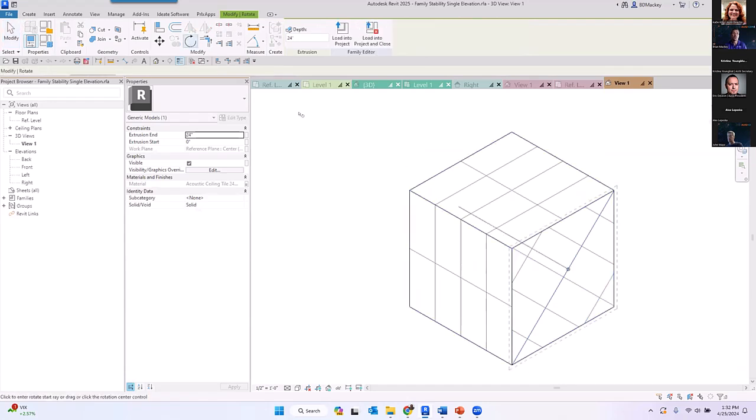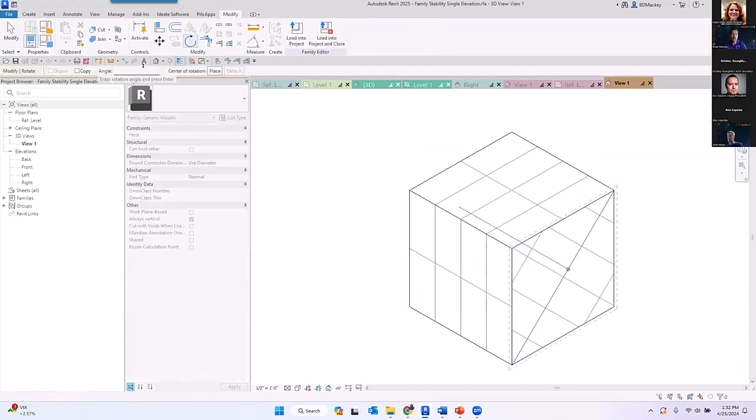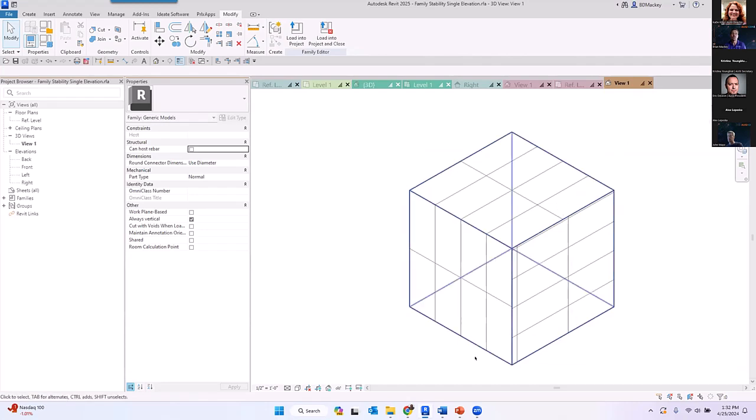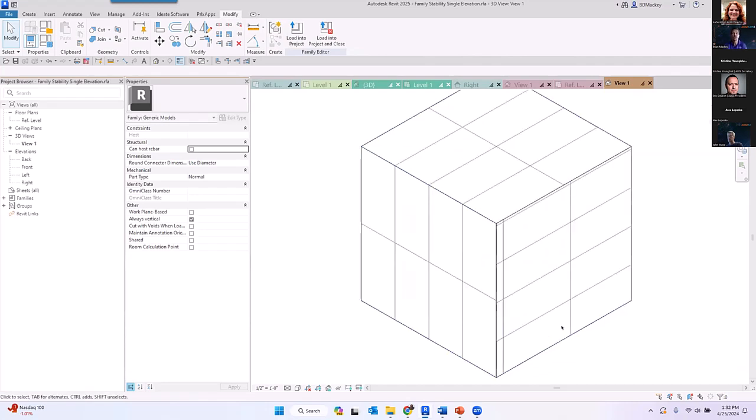And if you rotate that hatch pattern, that's not only going to be rotating any hatch pattern you put inside of there, it's going to say, that's where my rendering image is going to go. That's the directionality of my rendered images. So for me, and I know it sounds crazy, all my door families, if I have stiles and rails, I don't do those as a single extrusion. My door families, the stiles and rails are all modeled as individual extrusions. So therefore I can have control over how I want to rotate these materials.